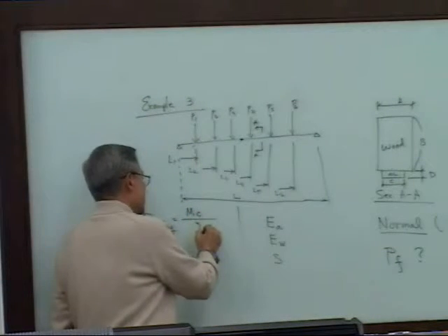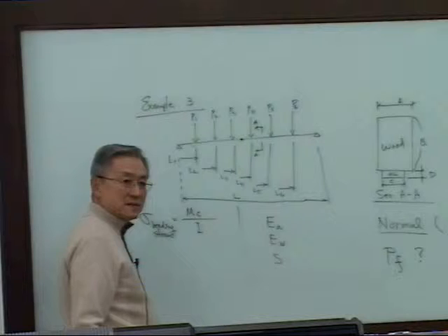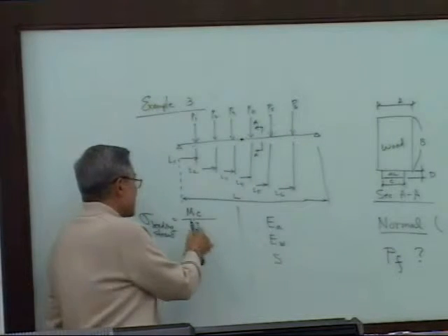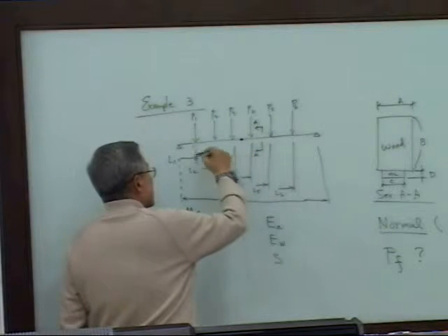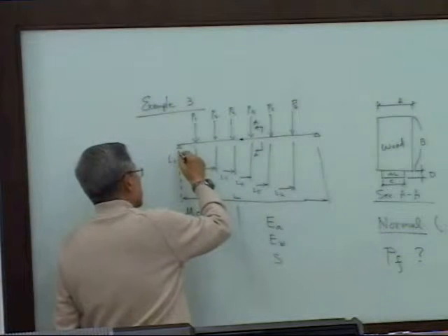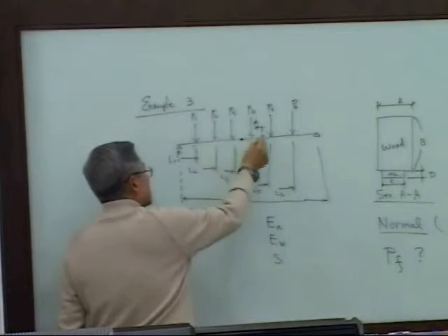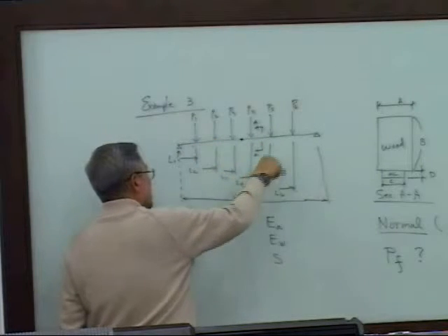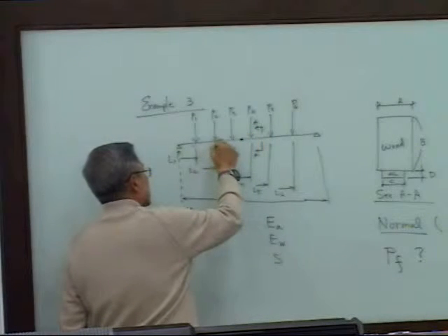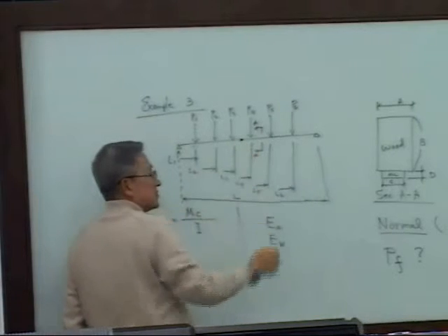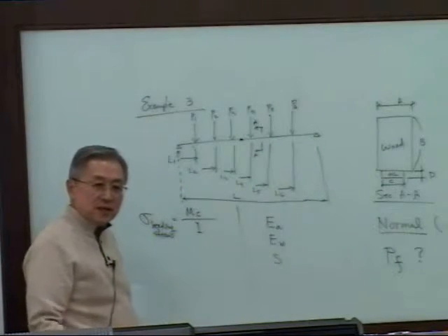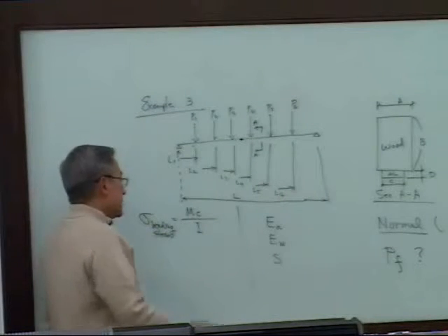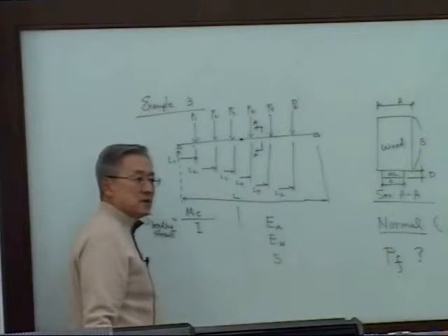So here the moment is right at that point at the middle. Then you can compute the moment from the reaction force, positive. Then counterclockwise is negative. And you will compute the bending moment at the center of the beam. Then C, what's the C value?